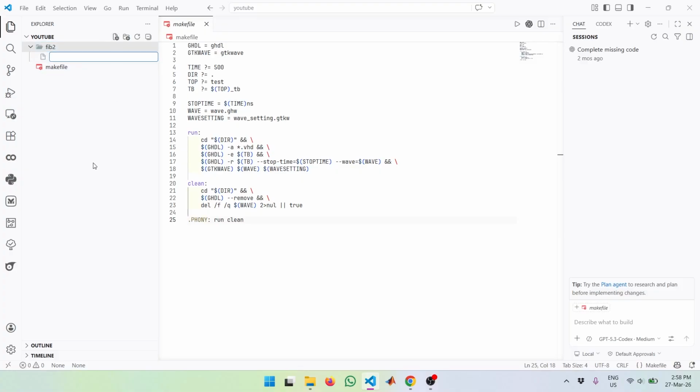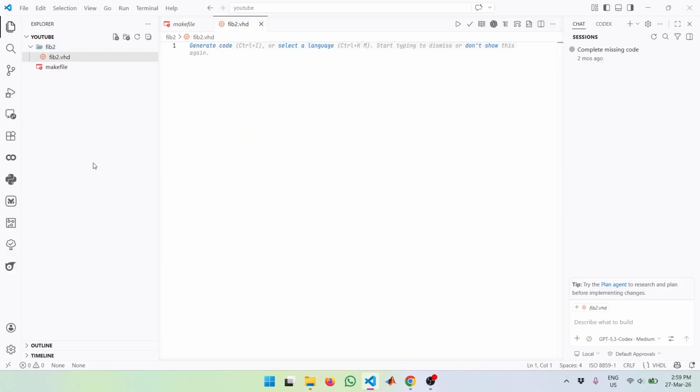Inside this empty folder, I'm going to create the Fibonacci main source code, fibonacci2.vhd, and together with this one, another file for the test file, fibonacci2_testbench.vhd. So in the main implementation for the Fibonacci series, I will be making the input and output an integer.